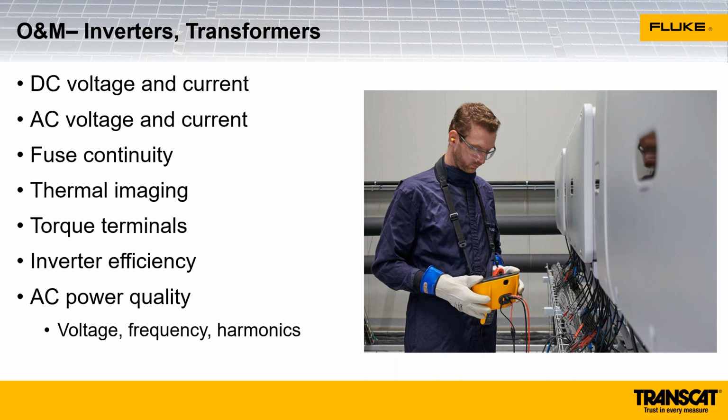Torquing terminals is really important. Terminals should be torqued when the system is installed. That should be part of the commissioning process, as well as checking those terminal torques. If terminals are under torqued, you can have high resistance connections. High resistance leads to heat, and heat eventually leads to fire.